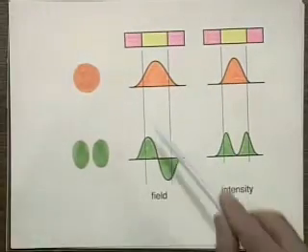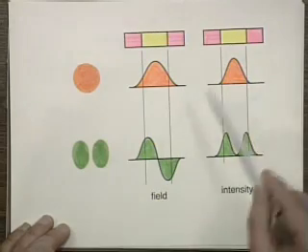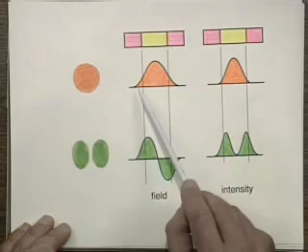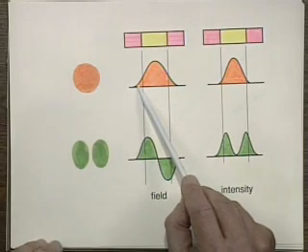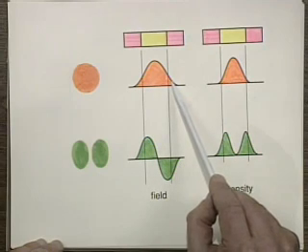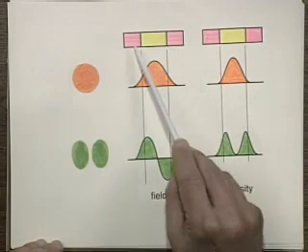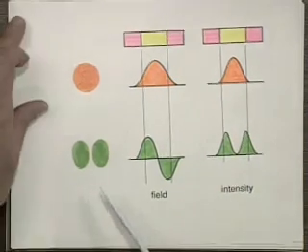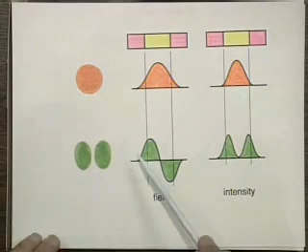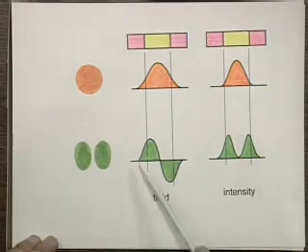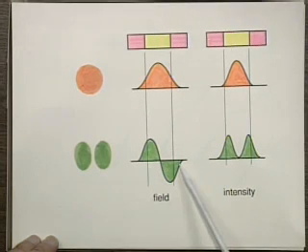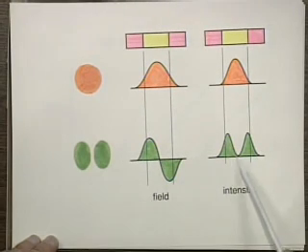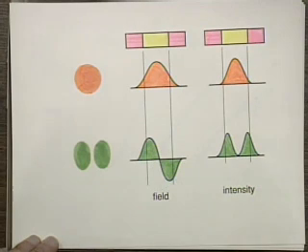In this particular case, what I show you is the field distribution and the intensity distribution in the fiber. Here's the core, here's the size of the core, and that's the cladding. And you can see here, depending on the parameters that I choose, some light in this lowest order mode in the field will propagate in the cladding, and so will essentially the intensity. For the next higher order mode, which is similar to the laser cavity modes, the field distribution is something like this, and again, part of it will propagate in the cladding. And when you square it up, if we look at the intensity, it looks like this. That's what these two spots look like. But the field is really, let's say, one positive, the other one negative.